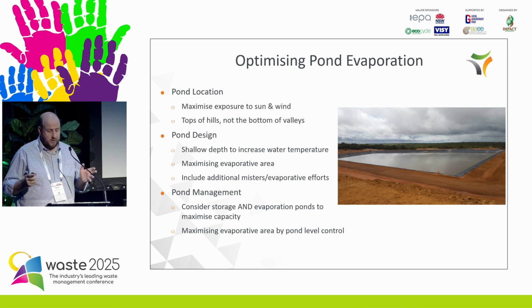For storage, on many sites we've worked on, we have big storage ponds with small surface area, as deep as we can get them. But then on the side we have large, very shallow evaporation ponds. So when we are pumping the leachate in there, it can heat up nice and quick and we can get rid of it. So be very mindful that we're thinking about how we are designing our ponds. And realistically, if you are looking for evaporation, it should be ponds.